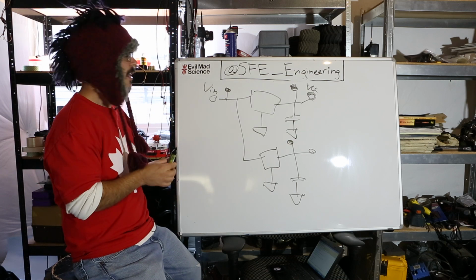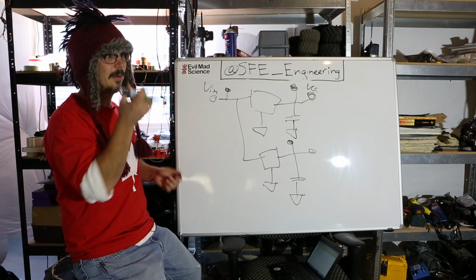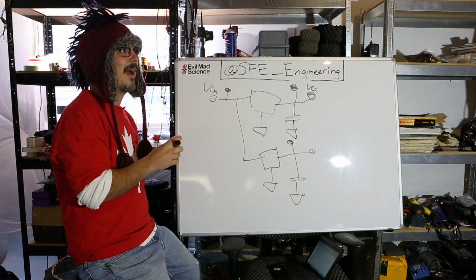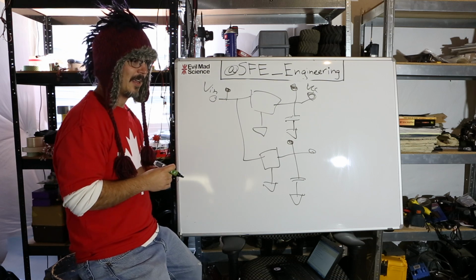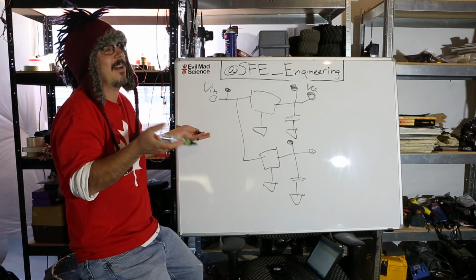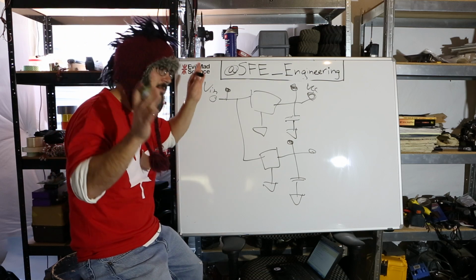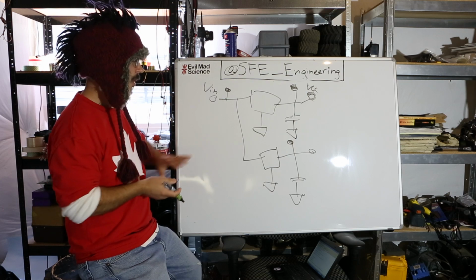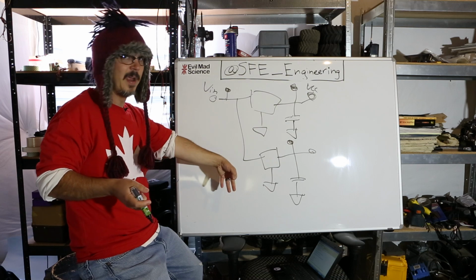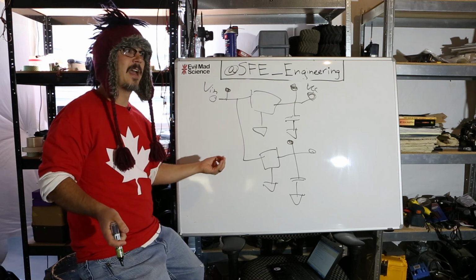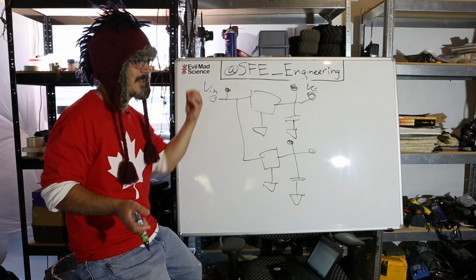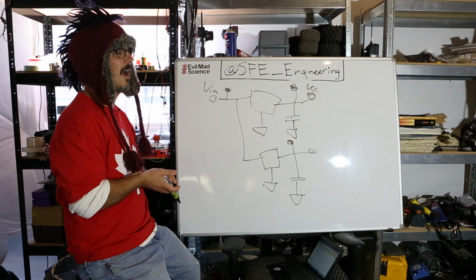that stuff goes bad sooner than electronic stuff does. So in a production setting, you're going to want to be putting, for example, I've got an antenna that's like an active antenna that's got an LNA in it. For example, it's got a GPS antenna, just for example. You might want to measure on a board that you've designed that the output at your SMA or UFL connector is actually at the power that it's supposed to be, okay? And you might want to put a load resistor in your test apparatus to make sure that it's going to source as much current as you need it to be.